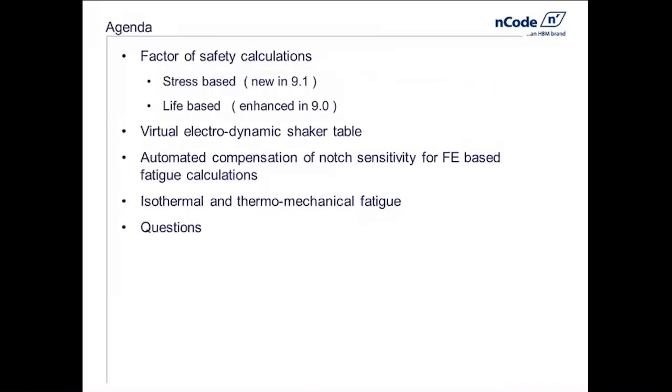Today we're going to look at certain capabilities inside of DesignLife to enable those styles of calculations. We'll look at factors of safety, both stress-based and life-based, and I should mention today that the stress-based are new in 9.1. Everything else today is going to be current 9.0 or before.